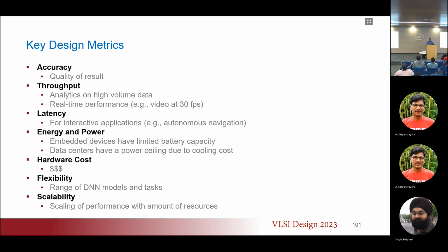In the process, what happens if I misclassify a pedestrian as a poster, and in the next time frame I find that this object moved? Then I already know that it's a pedestrian. So did I have to be super accurate in classifying a pedestrian versus a poster? No, because I have redundant information from one frame to the other, there is only limited displacement of that object, and I'm doing motion tracking.